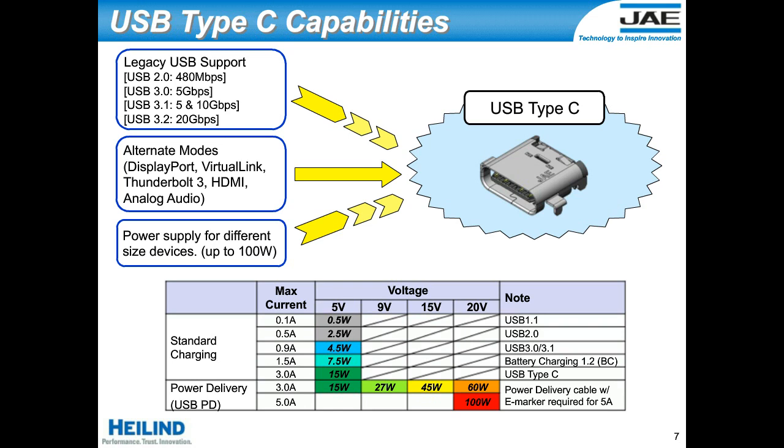However, one thing it is important to note is that USB is a DC power supply only. So for some of those devices that have internally integrated AC-DC conversion, Type-C cannot be the cable for that. You'd have to have a power brick or a wall adapter that changes to DC external to the actual device.